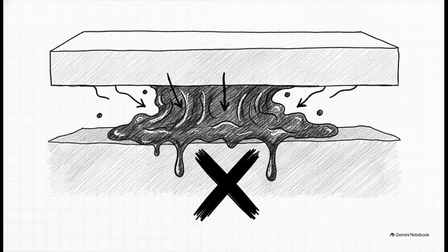But listen up, because you have to be incredibly careful here. Henry 430 Clear Pro is a fantastic adhesive for vinyl composition tile, sure, but you must absolutely never use it for solid vinyl tiles or vinyl-backed modular carpets.